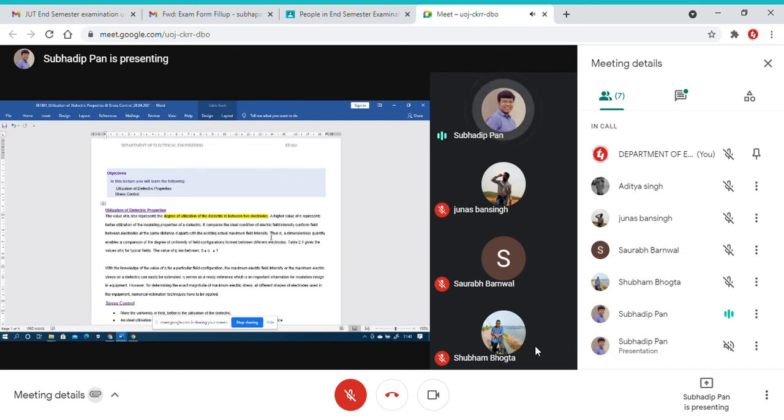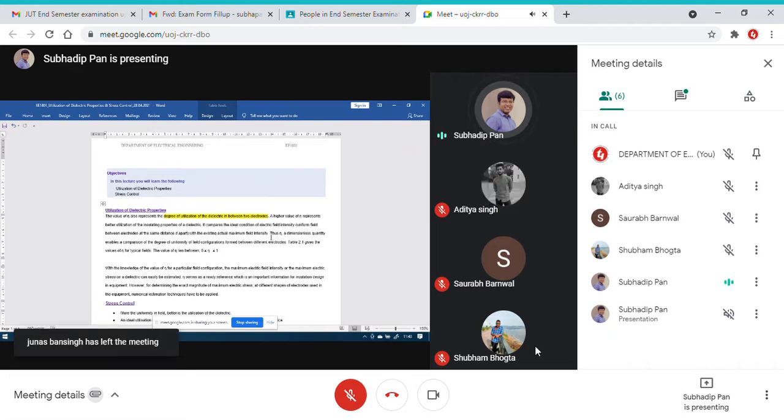Okay, so it compares with the ideal condition of the electric field intensity, which should obviously be a uniform field between the electrodes at the same distance d apart. d is the distance between the two electrodes, either A to B or B to A. We also discussed in the previous lecture the case where the electron flows from B to A. For that case, the work done is defined as U of AB equals the integral from B to A of E dx, which is phi A minus phi B, where phi is the potential.